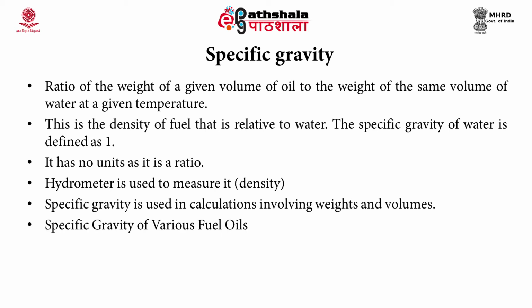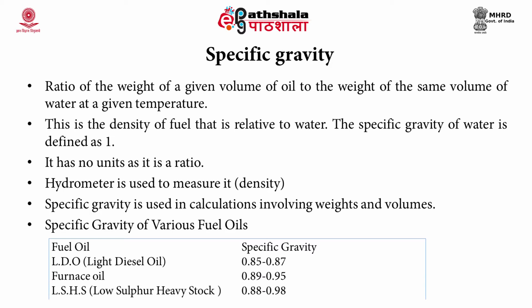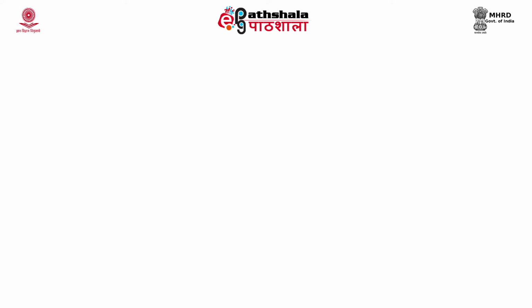This table shows the specific gravity of various fuel oils. Light diesel oil has a specific gravity of 0.85 to 0.87. Furnace oil has a specific gravity of 0.89 to 0.95. Low sulfur heavy stock oil has 0.88 to 0.98. Another important property is the viscosity.